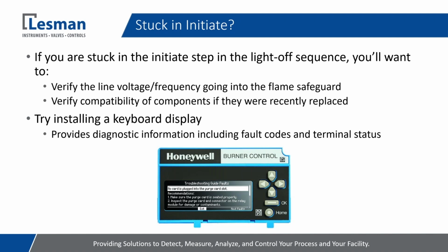Again, with the Honeywell 7800, the keyboard display is not a requirement, but it's highly recommended. You can get a wealth of diagnostic information when you put one of these on. The one that I actually show here in my presentation is a slightly newer model that Honeywell released just a couple of months ago.